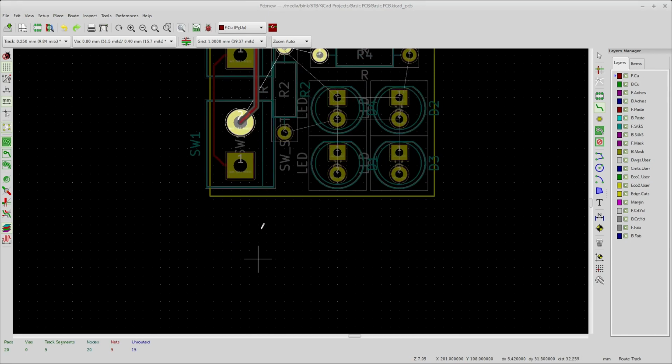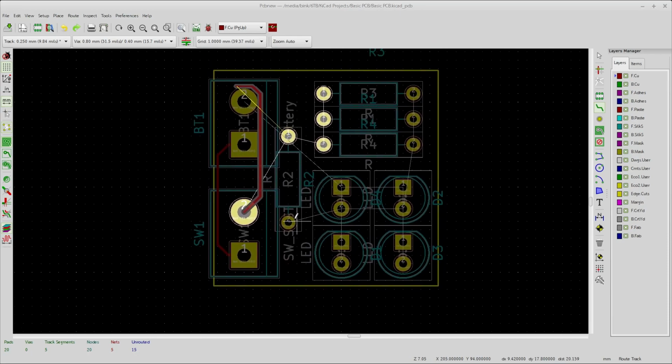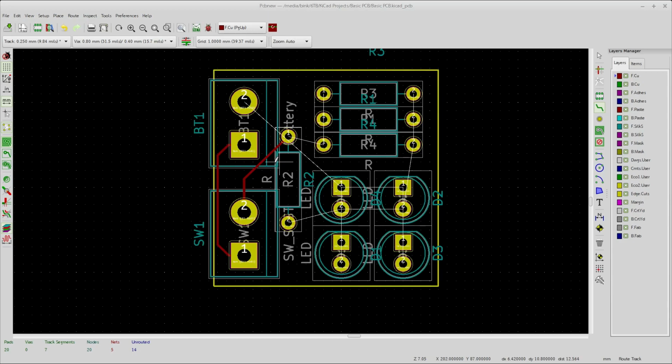So try to keep everything about as tight over to this side as possible, because you can see that I'm almost done routing this side. Nothing needs to go over there. So if I try to keep it there, there we go. Double click and it stops it. By the way, you see the little extra lines around here, and when I'm drawing it, there's an extra line around there. That's because of your design rules. By default, it's an edge spacing, an edge margin between your tracks, your routes, and any other components.